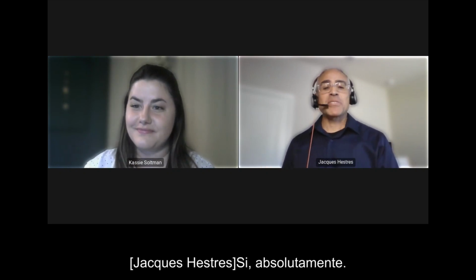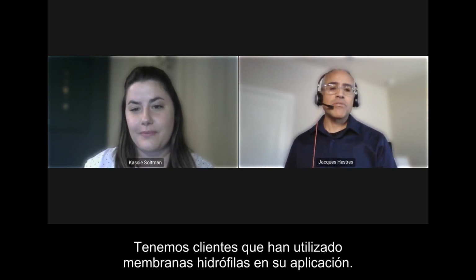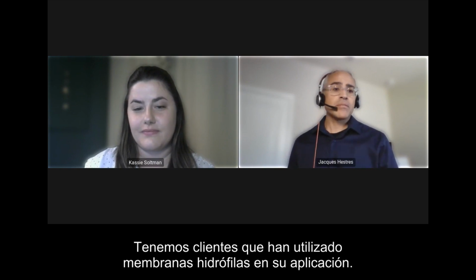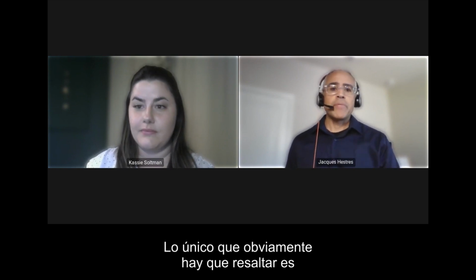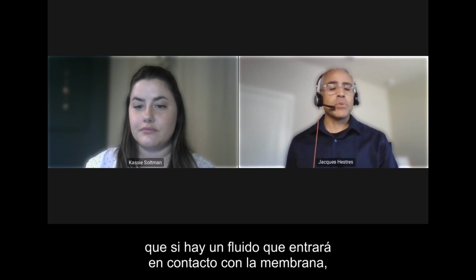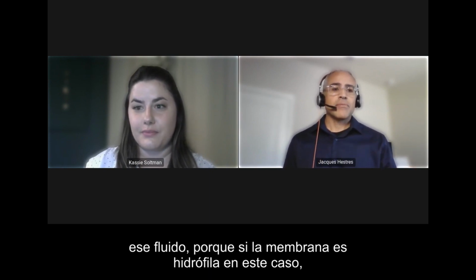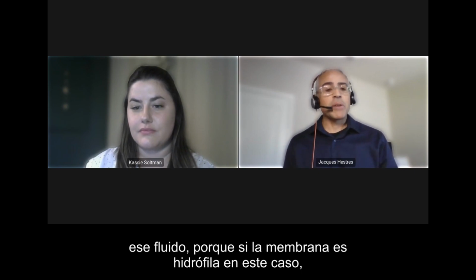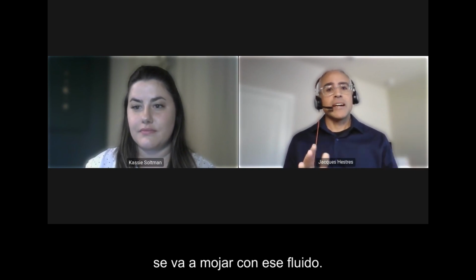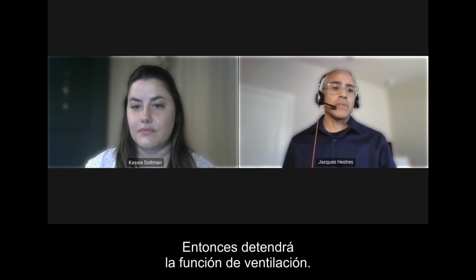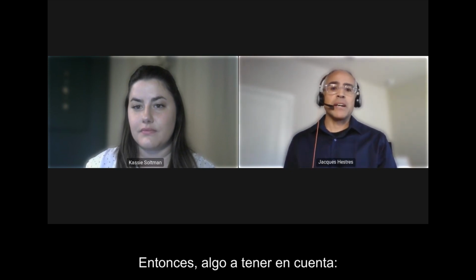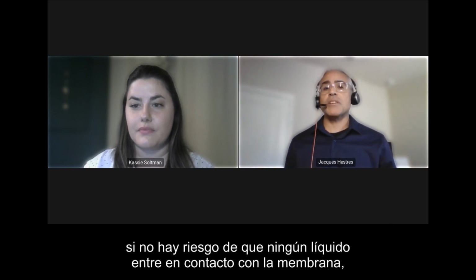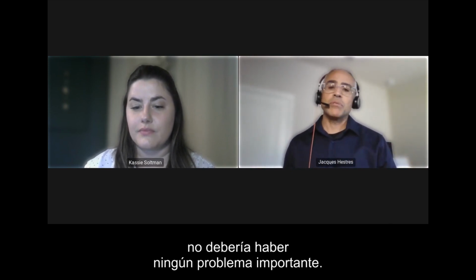Yes, absolutely. We do have customers that have used hydrophilic membranes in this application. The one thing to highlight is if there is a fluid that will contact the membrane, because the membrane is hydrophilic, it's very well going to wet with that fluid, so it's going to stop the function of the venting. So just something to keep in mind. If there's no risk for any fluid to come in contact with the membrane, there shouldn't be any major issues.